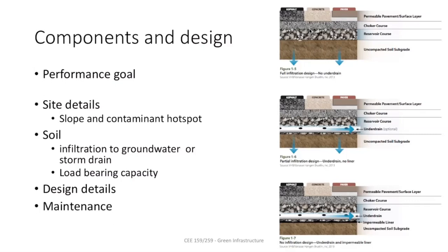The last one, or more important, something that we don't often think of, is the intended use. If the permeable pavement is just for walking, then it doesn't have to have high loading capacity. But if it's a road where cars will be parked, then it needs high load capacity. So you have to design all those systems in such a way that they don't destroy the permeable pavement. It should bear that load.